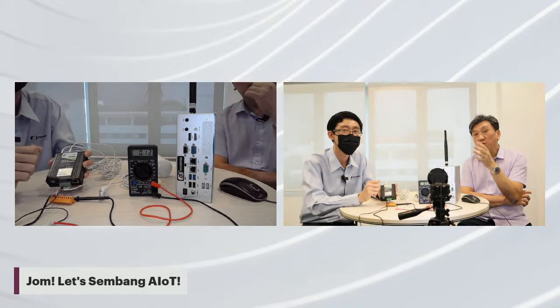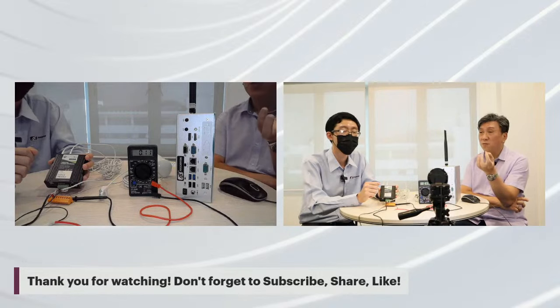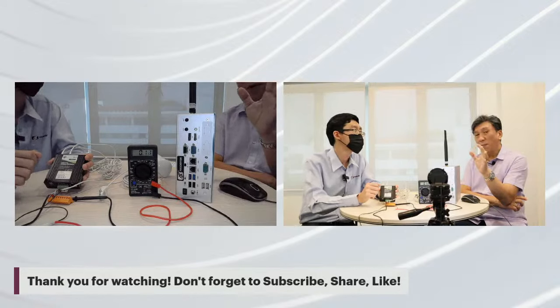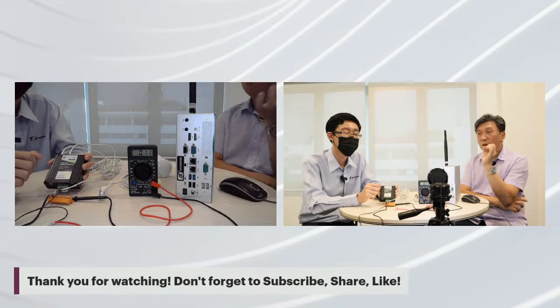For those of you who have experience with 2G, 3G, and 4G, right now I think 4G is a valid and more sustainable kind of application. Of course, no need to use 5G. Most of your IoT applications you don't need 5G; they can be done within the 4G region. But a lot of people do not know what the current consumption is.